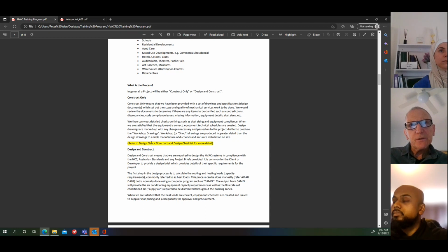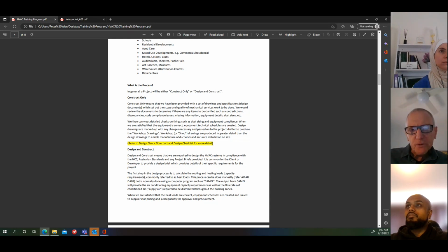And once the sketches are done, well, another thing we can do before we actually do that is to check that the equipment capacity specified looks correct. We can do that by taking the kilowatt capacity of the equipment divided by the floor area that it serves, which will give a figure of watts per square metre. Then we can see whether that looks high or low, and you'd have to talk to Ivan or Philip or myself to see initially whether you think that's correct. So, for instance, if it works out at 100 watts per square metre for an internal zone, that's probably about the right number.